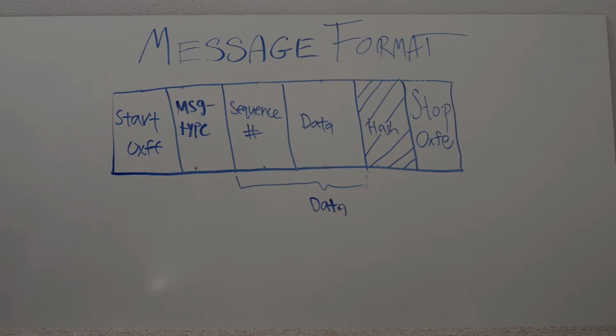Our last byte of data was 0xFE in hex, or 254 in decimal, which is used to signify the end of the message. The start and stop byte were used to prevent junk data. Our second byte is for the message type. This differentiates all the different types of data, such as the front sensor, both of our side sensors, motor commands, and acknowledgements.